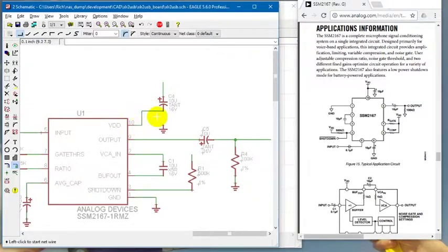I created this net, and in Eagle you can use the eyeball command and look down here in the bottom corner as I click stuff, and it says net $N$4. This one's $N$1, $N$2. $N$ means it's a net with an automatic name. They all have to have unique names, but that doesn't mean they have to be useful or important. So automatic names just start with $N$. This guy here has $N$5.